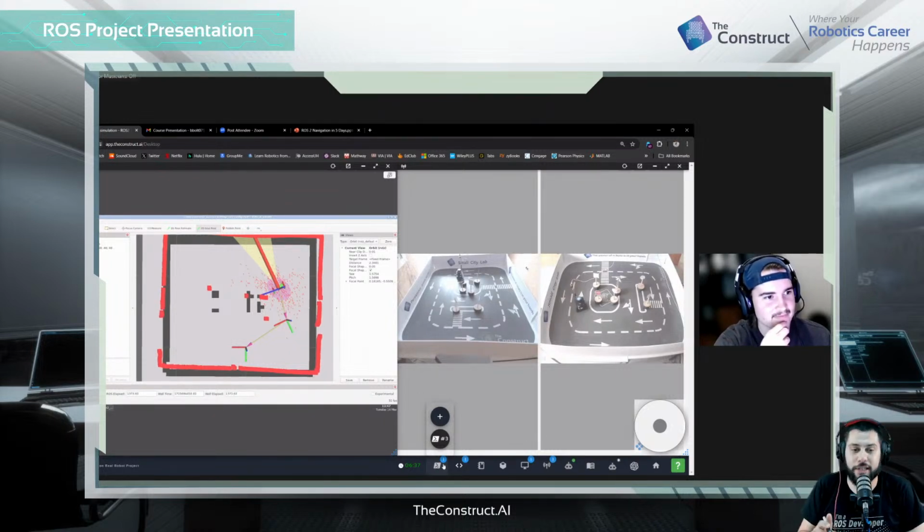But the actual reason is that the AMCL node only publishes the AMCL pose when it's moving. It needs to take in the change between the lidar and the odometry in order to publish that extra one. So you probably were trying to subscribe to it, but no new messages were coming in.